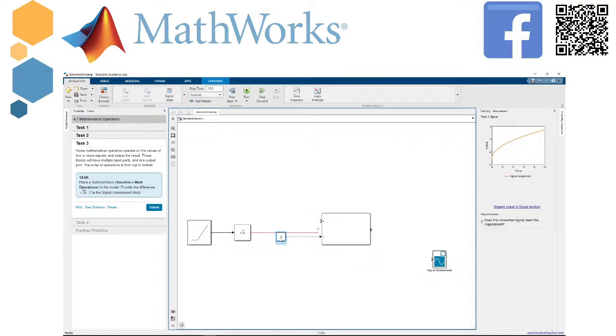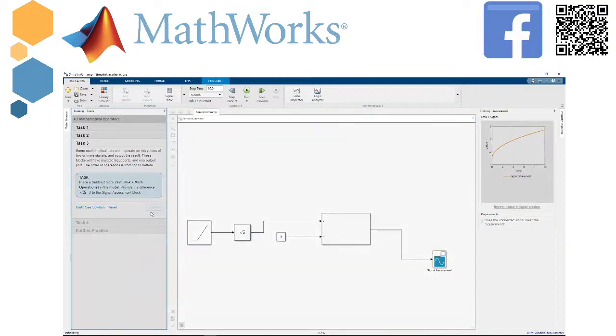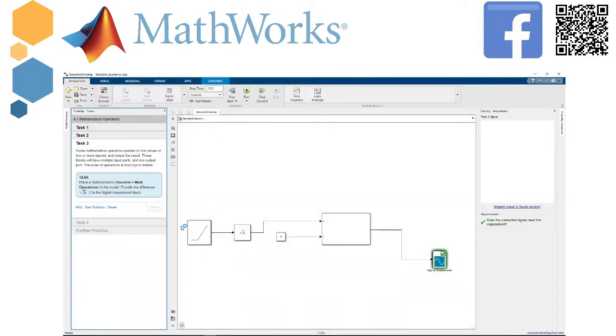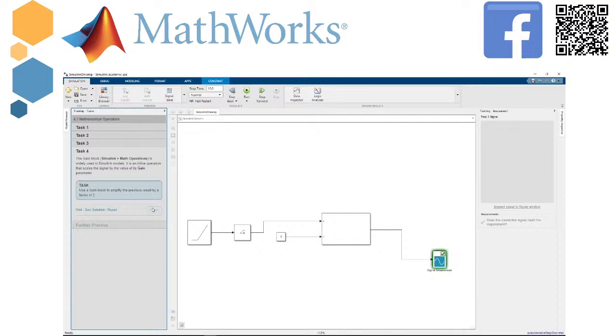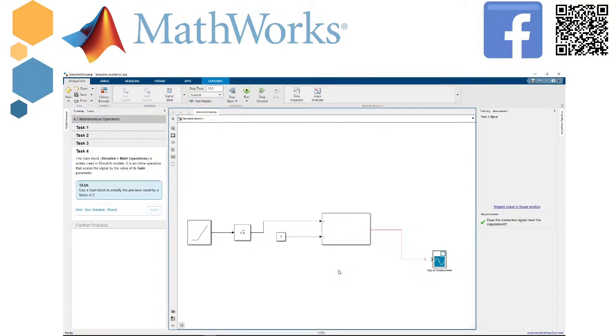Also copy and paste the existing sine wave block and change its frequency to 2 radians per second. Add a compare to constant block to the model and connect the 2 rad per second sine wave to it and to the scope block. So you can click Ctrl C to copy, Ctrl V to paste. We can change the frequency here to 2. Another copy and paste, and we can just connect. Set the parameter so that the block outputs 1 when the signal is greater than or equal to 0.1. So double click on it, greater than or equal to.